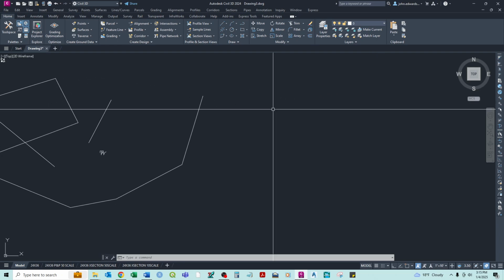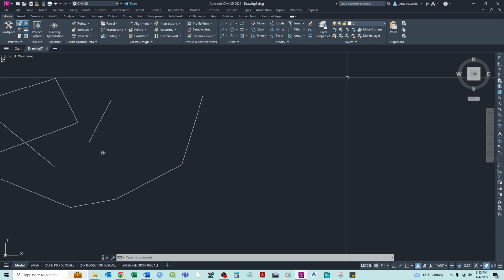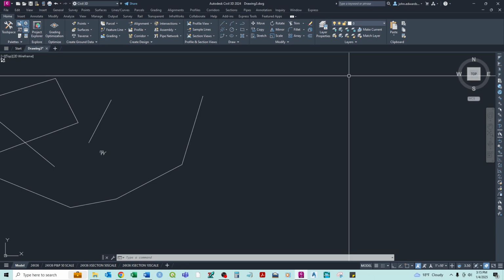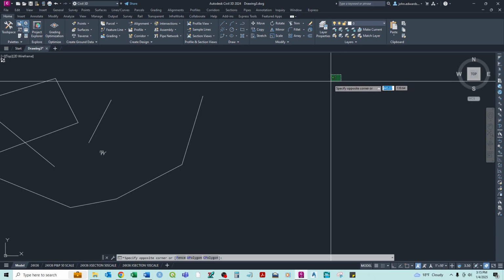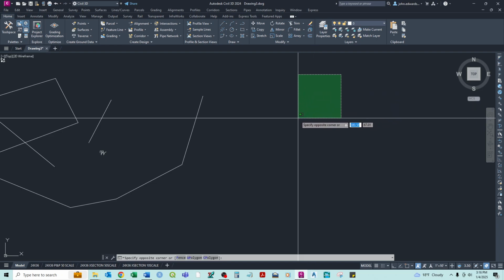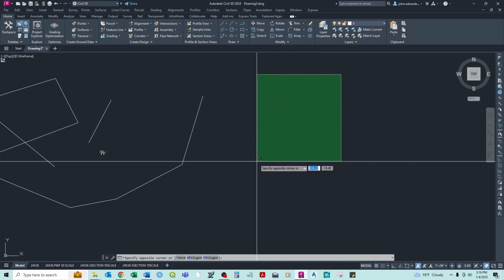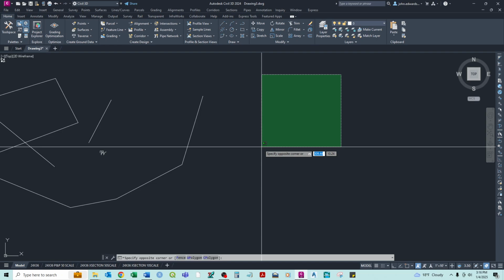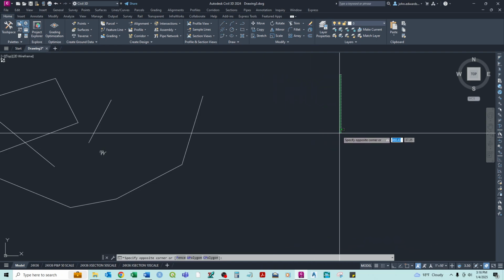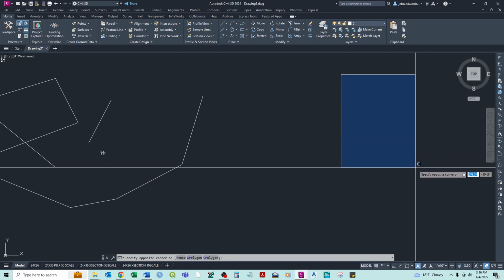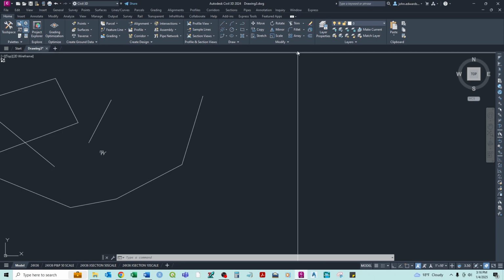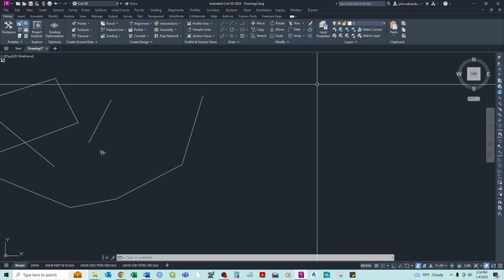So for example, if we come out here, and just to show you, I'm left clicking and holding, and you just left click into blank empty space, and you see how it's drawing in this window. Now the edges are dashed and the inside is kind of this green color, but when I go to the right, what happens? The edges are solid line and the window is blue. Now the thing I did a second ago, which I find very unwieldy, sometimes it can be helpful.